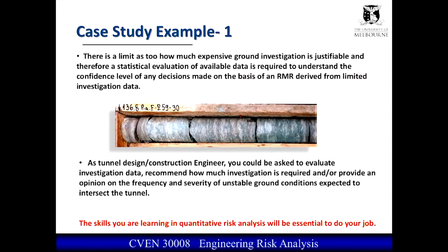And you've got to make a judgment call, because if anything happens, you'll be responsible. If you said, I think I can work from the few samples I've got, and I can tell you that there's no problem with the ground, or there won't be any problem until we get 100 metres in, or whatever it is. So here it is. You could be asked to evaluate the investigation data, recommend how much is required, and provide an opinion on the frequency and severity of the unstable ground, and give an opinion. So it's a risk assessment.